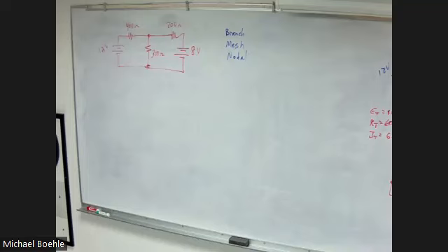Now, nodal analysis is going to involve determining how many different nodes there are, because I can find the voltage between 2 different nodes, 2 different points. A node is a point. It's a point of intersection between components, branches. So how many nodes are in that circuit? 6.